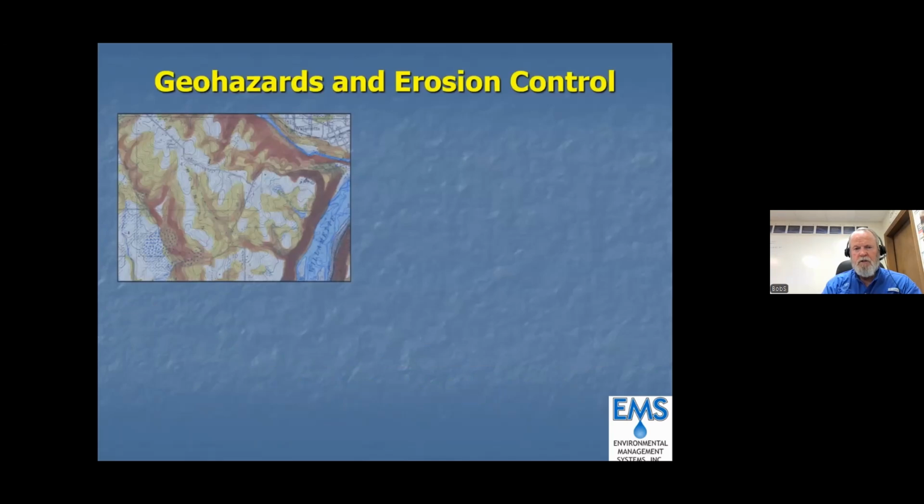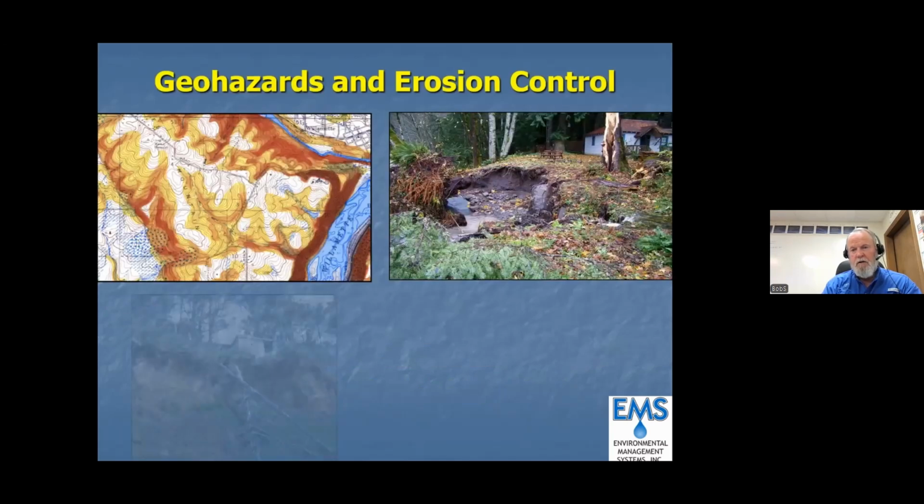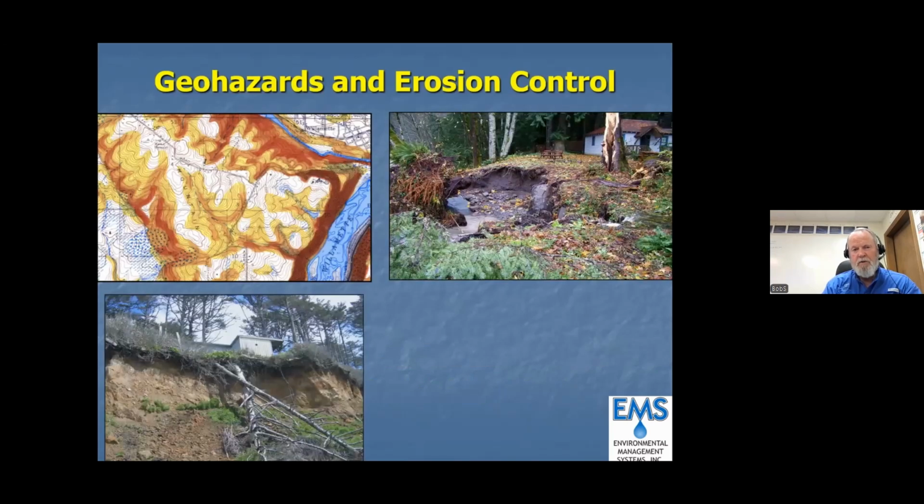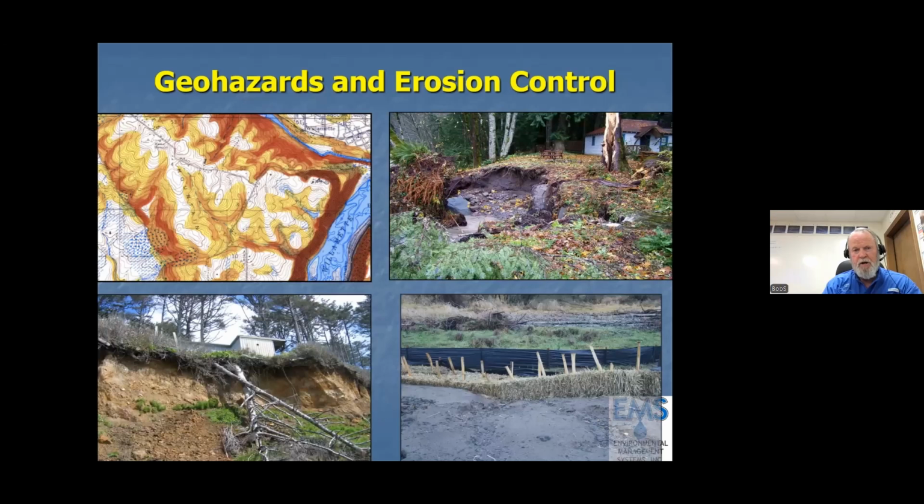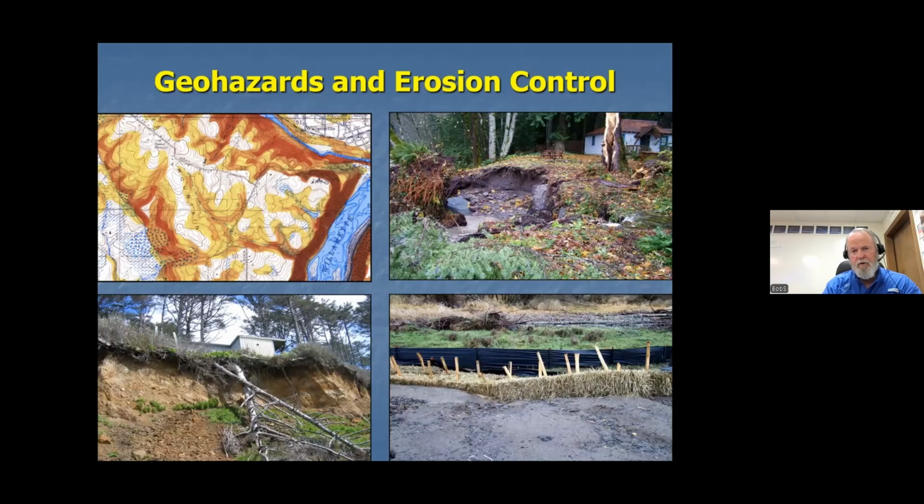So we're also looking at the site and what has happened to the site from drainage. You're looking at some geologic maps. You're looking at what has been eroded near the streams. The site on the upper right, it used to be a stream that was 30 feet away, and now it's 10 feet away from the site.